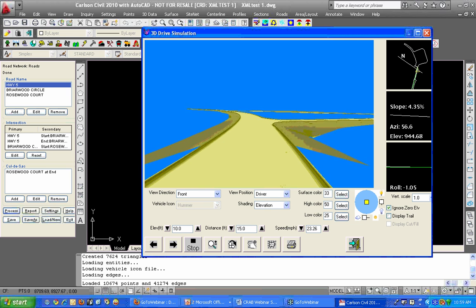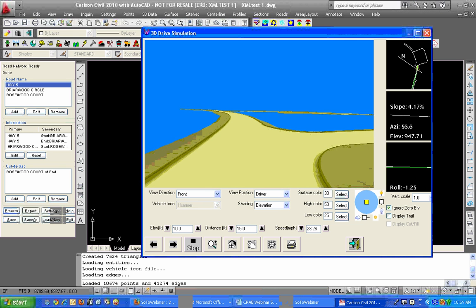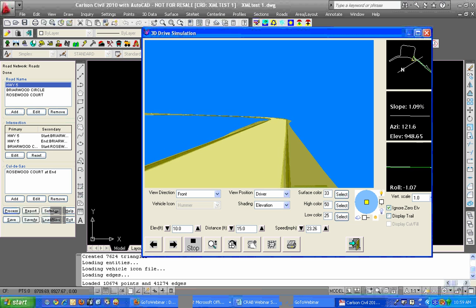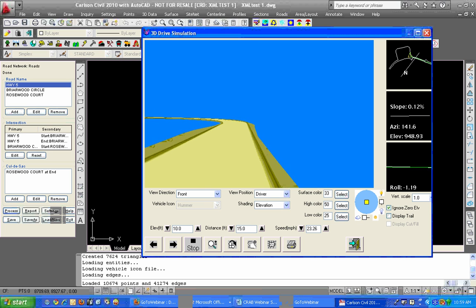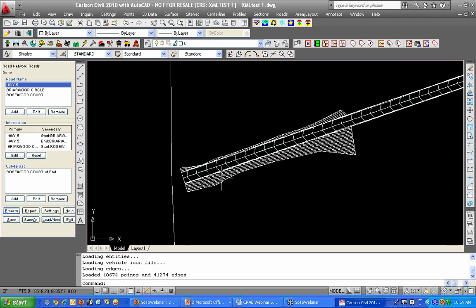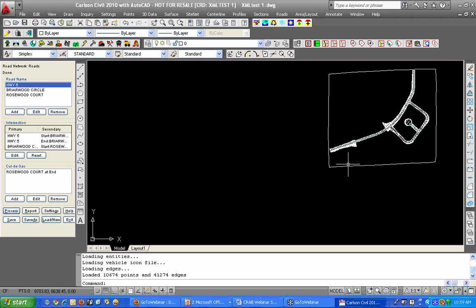You can also use 3D polylines to control your route. Oh, falling off the road. In which case it would simply track along that 3D polyline. So I could actually draw out the route that I want this to take using a polyline, project it to the surface, and follow that.